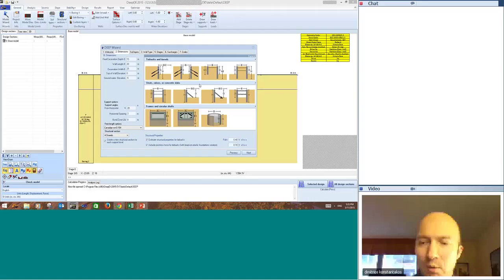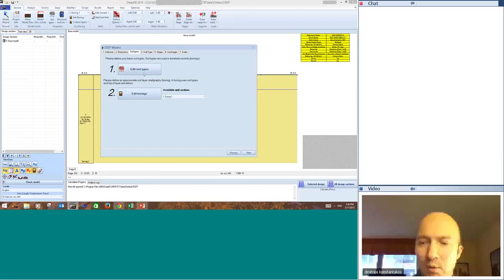So next, we're going to start with a 10-meter excavation, a wall length of 15, an excavation width of 12, and we're going to do a full cofferdam here, the groundwater at -10, and one wall length 12 meters, let's say the other one 22. And we're going to space our struts at 5 meters. We're not going to edit the soil layers at this time, but we're just going to say edit borings.